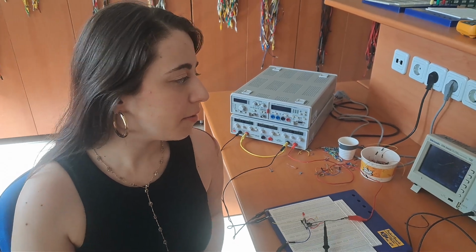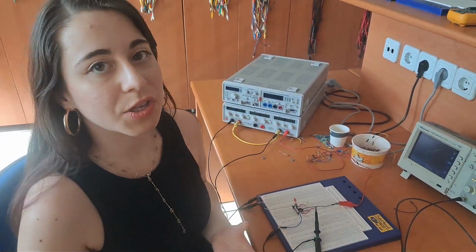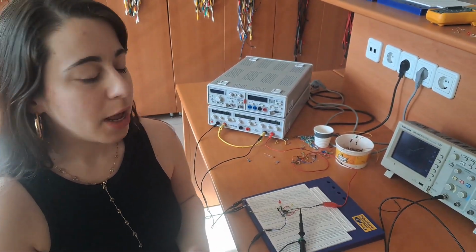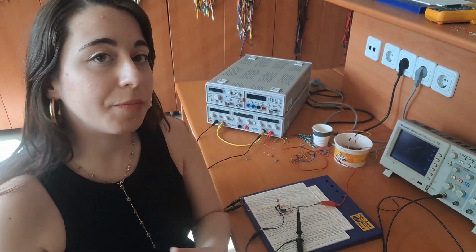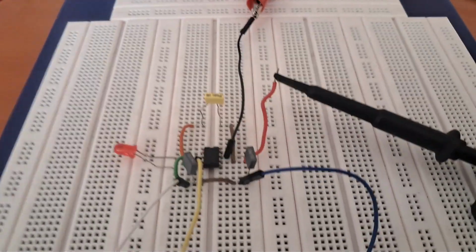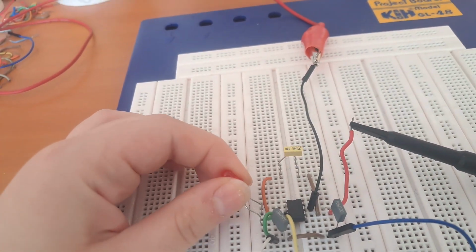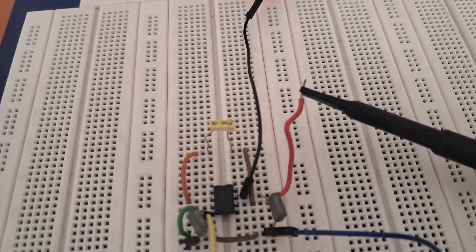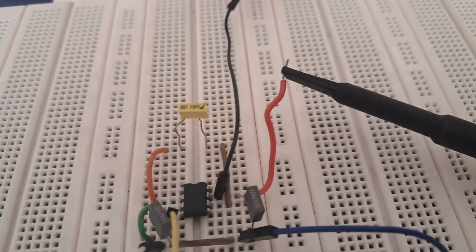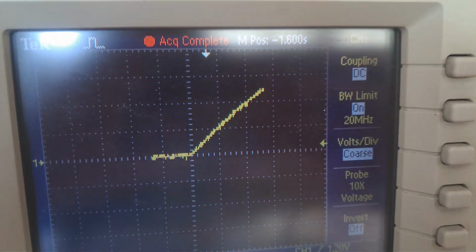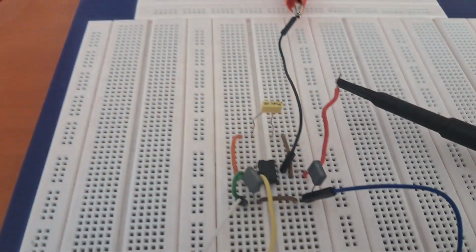But we never considered the fact that there's an input bias current. We assumed it's zero. So our photodiode currents aren't actually what we calculated. We have to calculate the input bias current and subtract it from our previous measurements to have a better result. For this purpose, I'm gonna remove the photodiode or LED, and now we're only gonna have input current coming from the op-amp. And I'm gonna short the capacitor again and repeat the same experiment to again calculate the slope and multiply it by the capacitance.